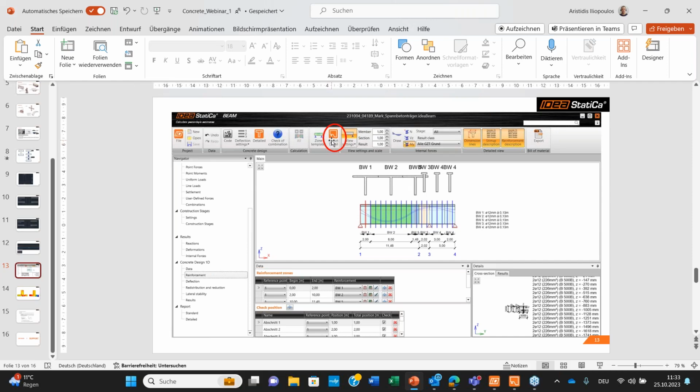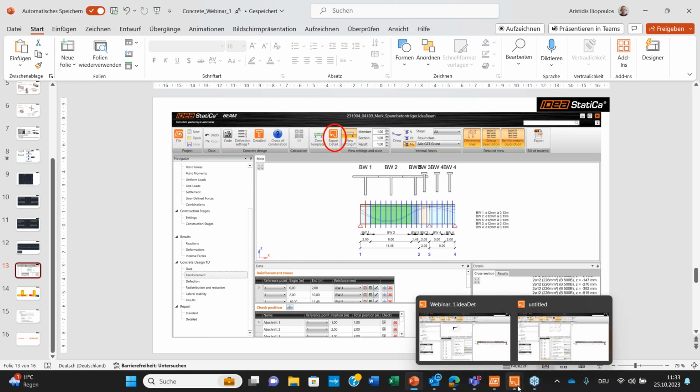If you do not have a simple supported beam and it is a continuous system, then it is also not difficult to find, for example, load combinations with the maximum bending moment or maximum shear. You can work with 5, 6, 7 maximum load combinations, but you can work the way you want. I know that there are colleagues and clients of ours that work with 10 and 20 and 100 load combinations, but I know that it takes time.